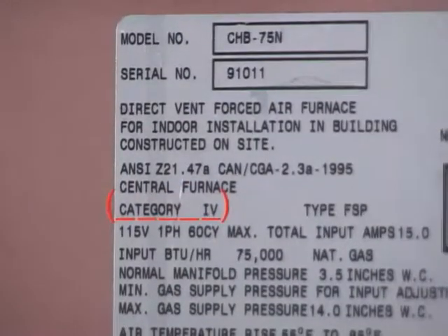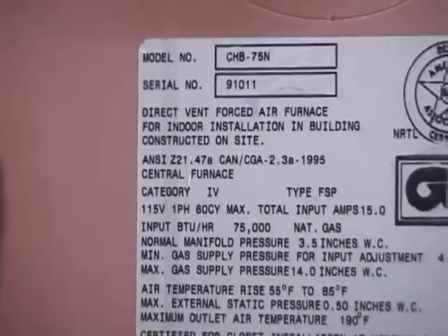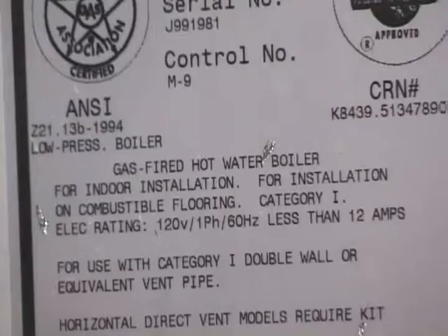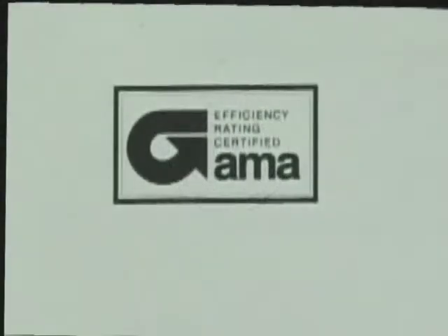Field technicians should understand the definitions of these categories, as the category of each appliance is on the rating plate. This tells the technician the general venting requirements of every appliance. Third-party testing laboratories verify that the appliance operates satisfactorily according to the category marked on the rating plate.